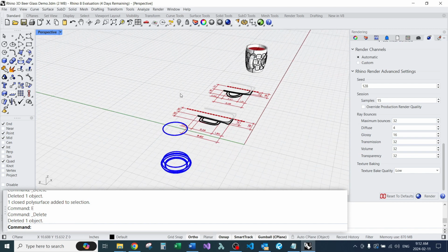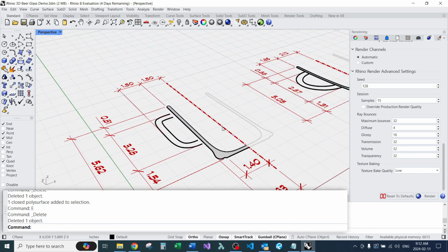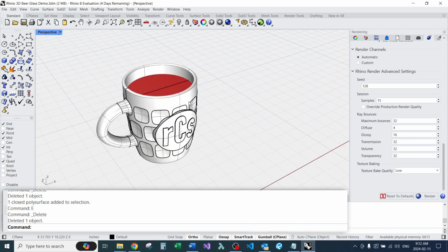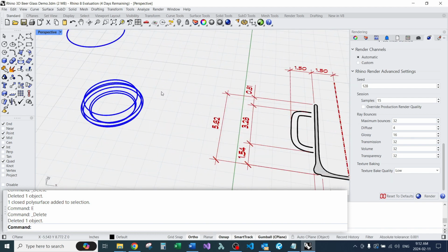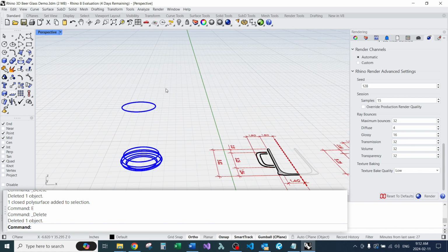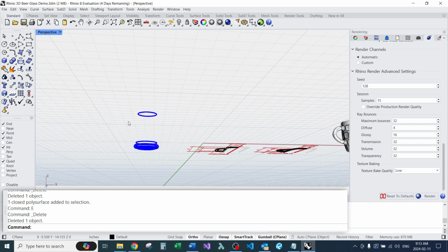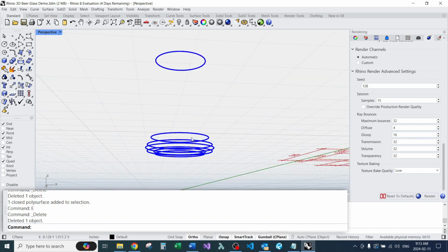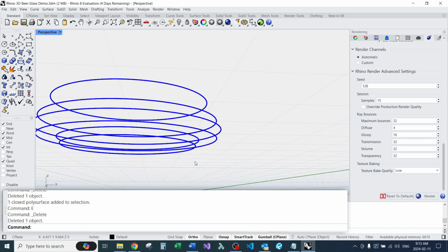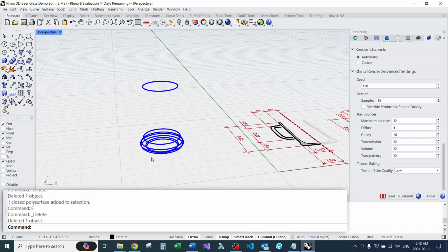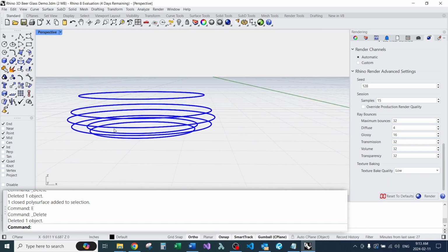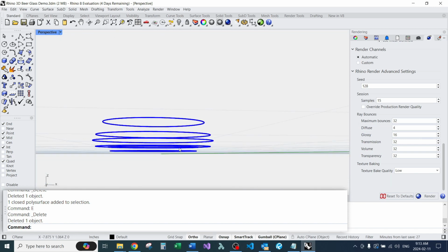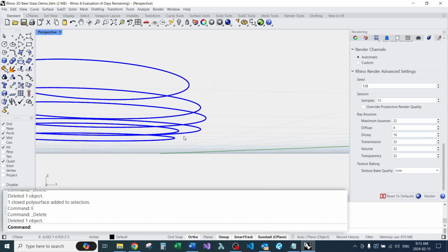So yeah, the revolve is one way to create a glass, but when I created this one, I actually used revolve. But in previous mini projects, I used the loft command, and that worked out better for me. And you'll see later that it also gives us an advantage when I create the contents of the glass. So I already have these drawn, basically using this as a guide. It's just a bunch of circles sized to roughly where I need them. So I'm going to loft them.